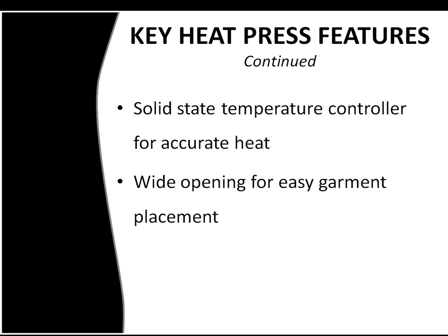You want to make sure that the sensor that's measuring the temperature of your heat press is very accurate, and that it is measuring it several times each minute, because that's what's going to essentially tell your heat press when it needs to heat up more or when it needs to cool down in order to ensure that you have accurate temperature.